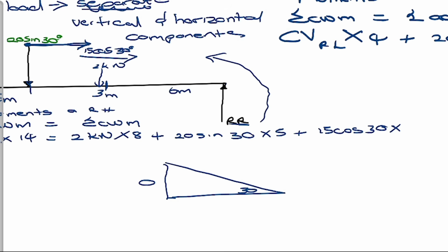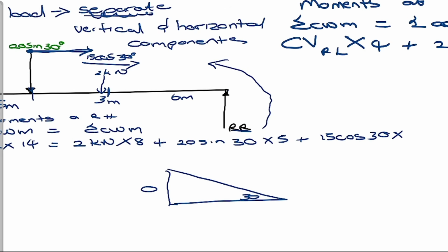And if you know this horizontal distance, you will probably find it if you draw your space diagram, I mean your load diagram, properly, because sometimes you're not given the measurements. You just need to draw your space diagram to scale, and then draw your load diagram to scale, and the load diagram has to be under your space diagram.